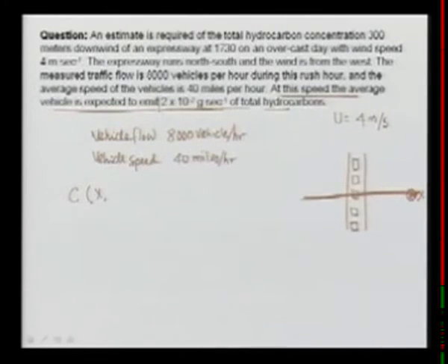We want the ground level concentration, so z is 0, and the height of the emission is also 0; I can consider the source to be at ground level. That formula we derived earlier was 2q over root 2 pi, sigma z u.